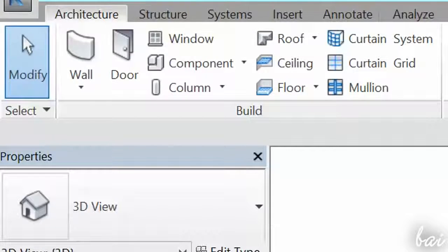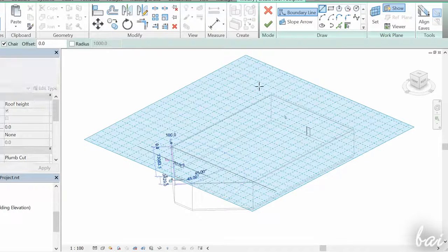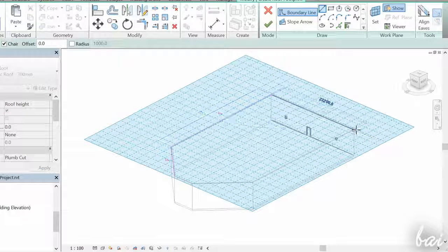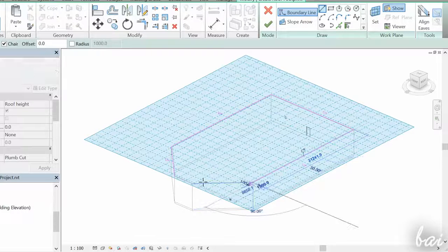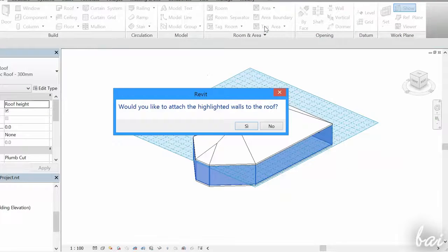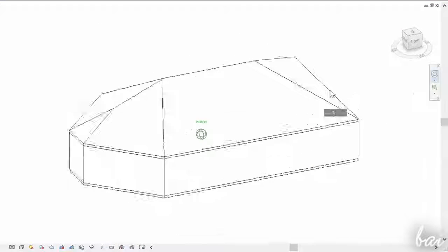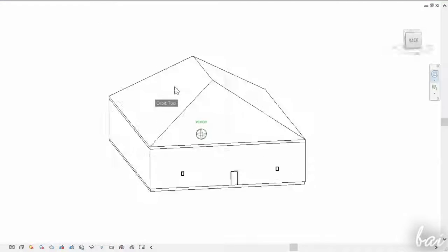Then, just enable the Roof tool and choose the drawing mode as seen for the floors and walls. Click on your workspace to fix the boundaries of the roof, and these will lay on the work plane just fixed. Once applied, you will exit from the Edit mode and you will see the roof rendered. By default, the roof will get a standard inclination of 30 degrees on all sides.